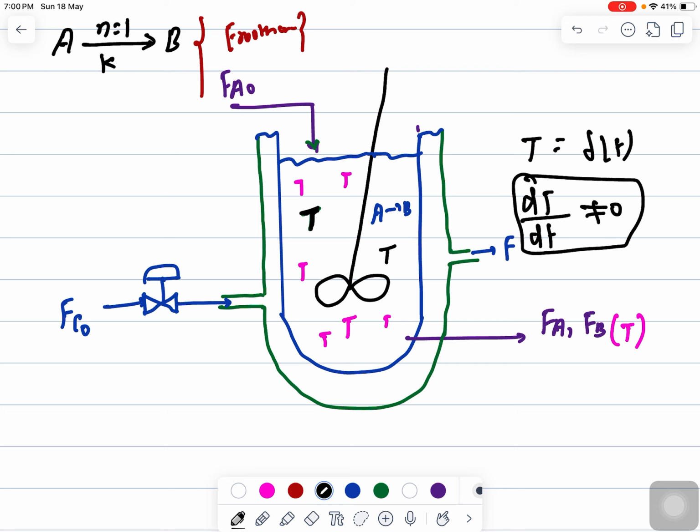But if you apply the energy and mass balance, what will happen? If the reaction proceeds, the temperature will rise. If the temperature rises, since this is an exothermic reaction, the reaction will not move along the forward direction. In order to maximize the product, you have to extract some amount of heat from the system, so that the system remains at that particular temperature to optimize the product yield, right? So now in order to do so,